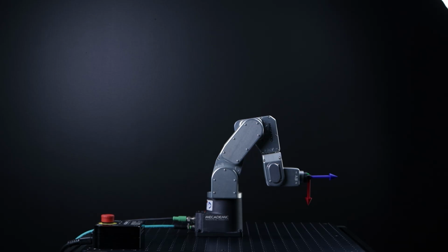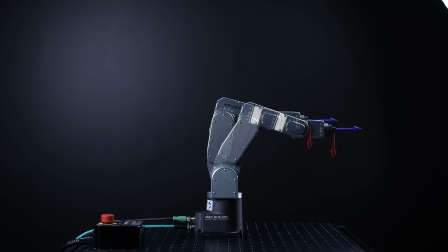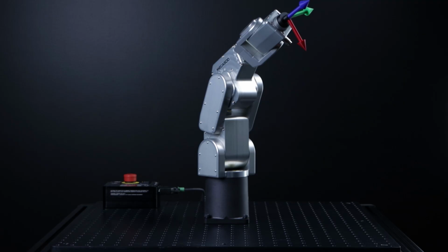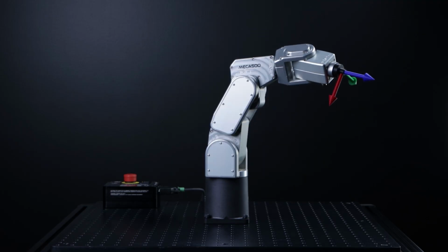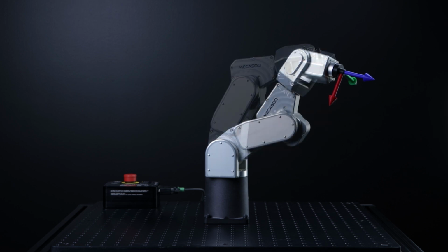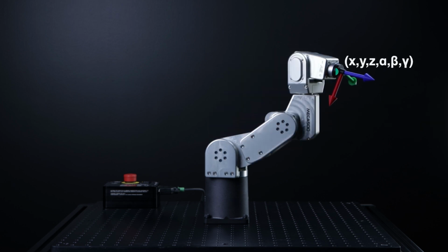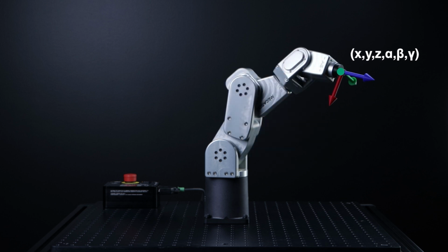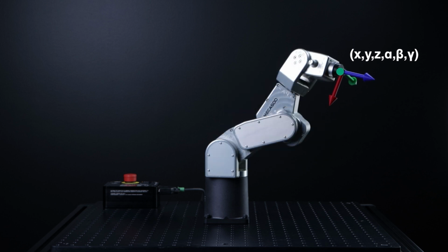We already discussed joint space commands and Cartesian space commands in a separate tutorial. With the move pose command, the robot solves the so-called inverse kinematics and finds different sets of joint positions that all correspond to the same target end effector pose. Each of these solutions is associated with a unique posture and turn configuration parameter.